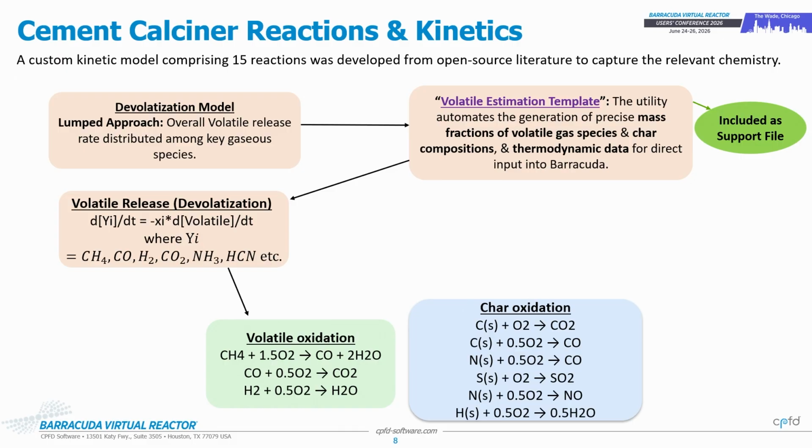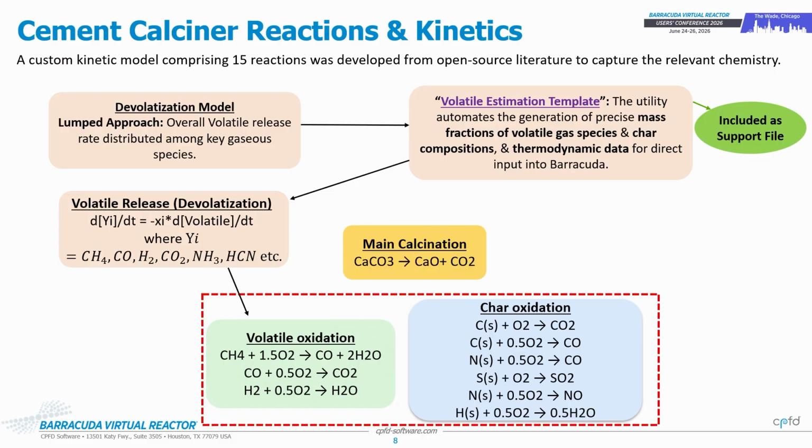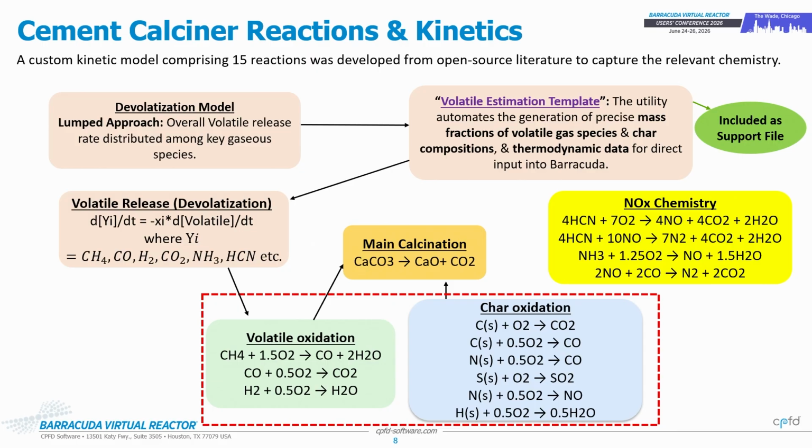I won't go into each reaction. And this constitutes the combustion reaction. And then we have the main calcination. We have the NOx chemistry. Both formation and reduction mechanisms are shown here. Also, we have the CaO, which is acting as a catalyst for one of the reduction mechanisms.